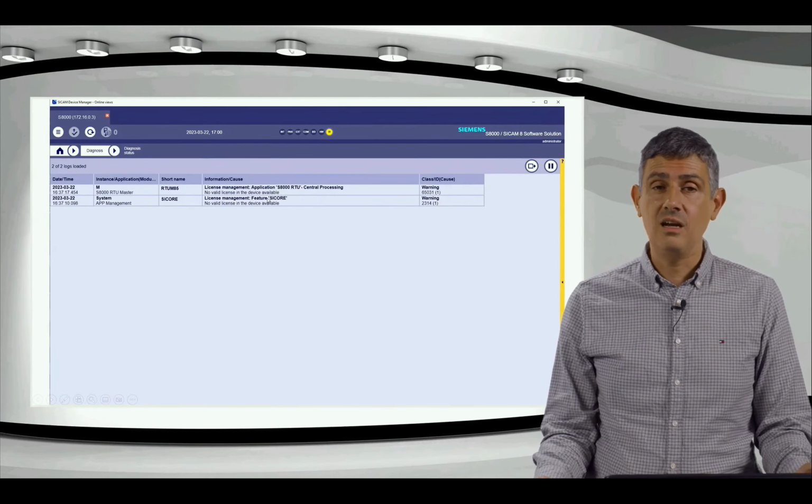And here I can just select the signals that I want to be included in the event list, which would be basically all the indications, all the commands, the alarms, and only the measured values are not there. And then I can just assign them to the event list through this button. They are here. Now we do the same for the alarm list. I will go to the alarm list. And then I select here only those signals that I want to include in the alarm list, like, for example, these protection trips. And then I assign them.